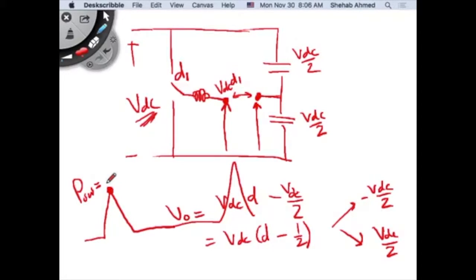So it's an optimization process, right? Do you want to live with 4 switches for a full bridge inverter and use less voltage? Or do you want to live with a half bridge inverter and use 2 switches, but then increase the voltage at the input, which means you increase the switching losses. If you increase the switching losses, you may need a heatsink, right? So the cost that you save on 2 switches, you may have to invest in a heatsink, right?